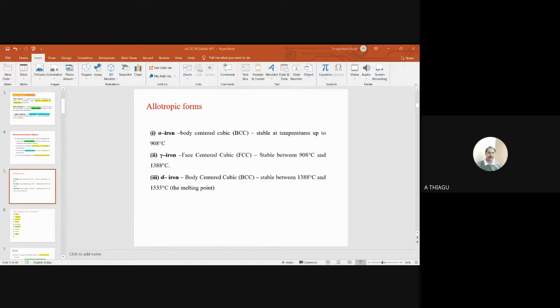I hope you can understand the different reactions. This is the last one, peritectoid, where also there is no involvement of liquid. Solid 1 and solid 2 produce solid 3. For particular applications like nickel, zinc, iron, uranium, copper, tin, molybdenum, these are good examples for the formation of the peritectoid system. Most alloy-based applications go for solid reactions only. So peritectoid and eutectoid are more involved in alloy-based applications.